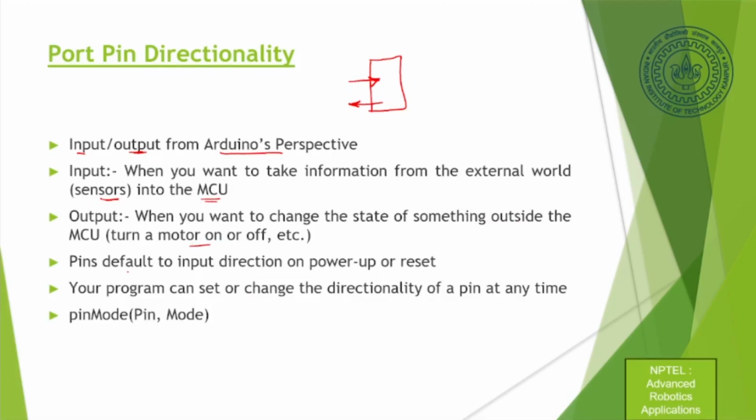Now, pin default mode: pins default to input direction on power up or reset. So the first time you connect it, all the pins are reset to the input direction. That means they only receive information, they don't give information. Your program can change the directionality of a pin at any time. You can set it as an input or an output pin.